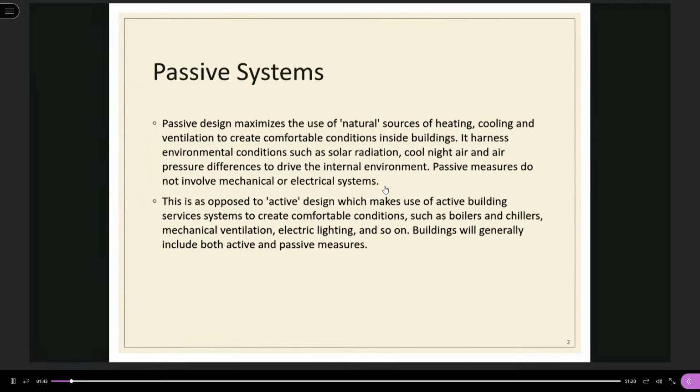So in the nighttime, the temperature difference between the exterior and the interior will be able to cool down the air. So in the daytime we have some delay time for the exterior environment to transfer the heat to the interior.